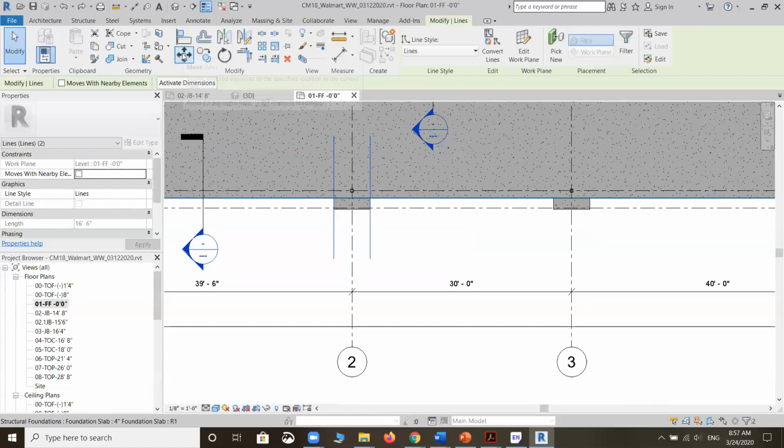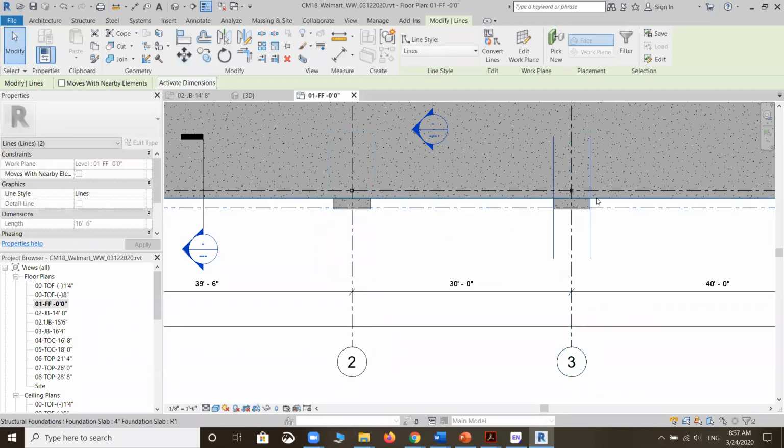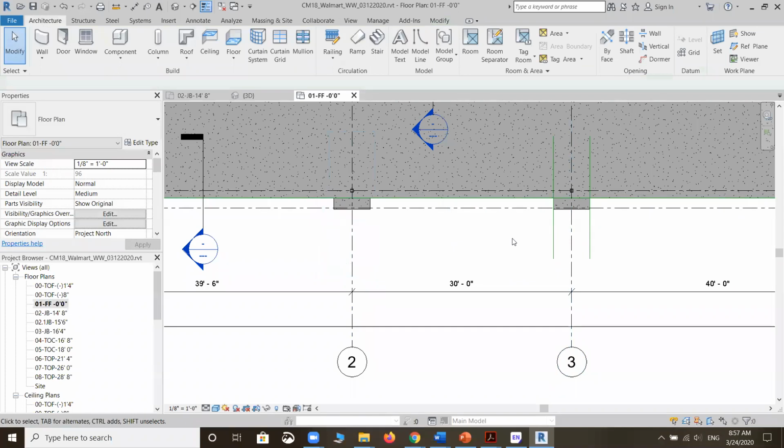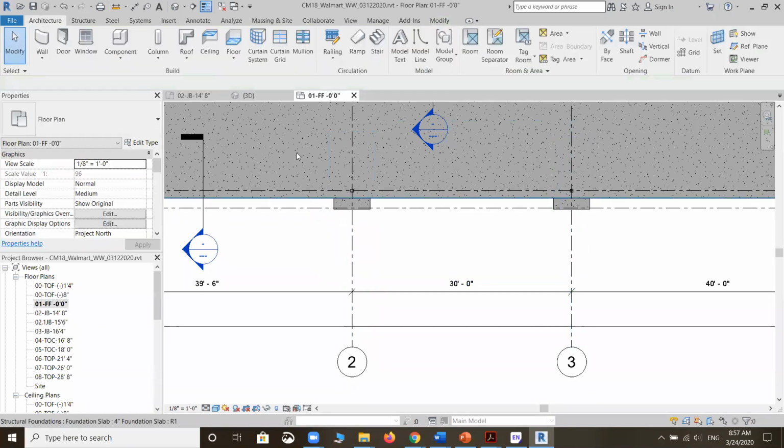Then you're trying to move these to the right place, so we use the Move command. I choose reference grid line 2, and then move it on top of reference grid line 3. That will move these two green lines here. Hopefully that answers the question. If you cannot figure it out, that's fine. We can delete them and just do it again.